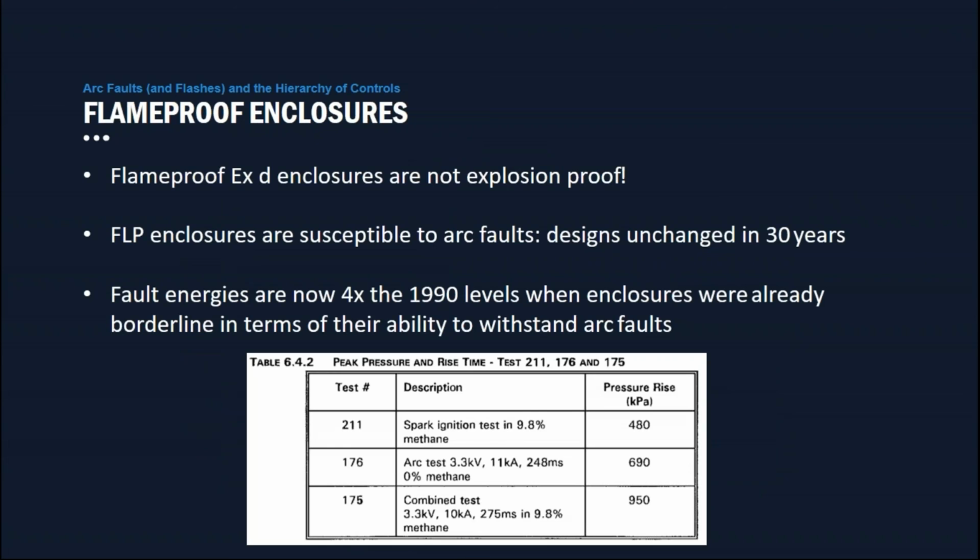So what about flame-proof enclosures? To date, we've talked about the standard IP enclosure. A flame-proof enclosure is not explosion-proof. A number of people think of a flame-proof enclosure as explosion-proof. They are certainly not. They are designed only to withstand the ignition of a volume of methane. They are not designed to withstand an arcing fault.